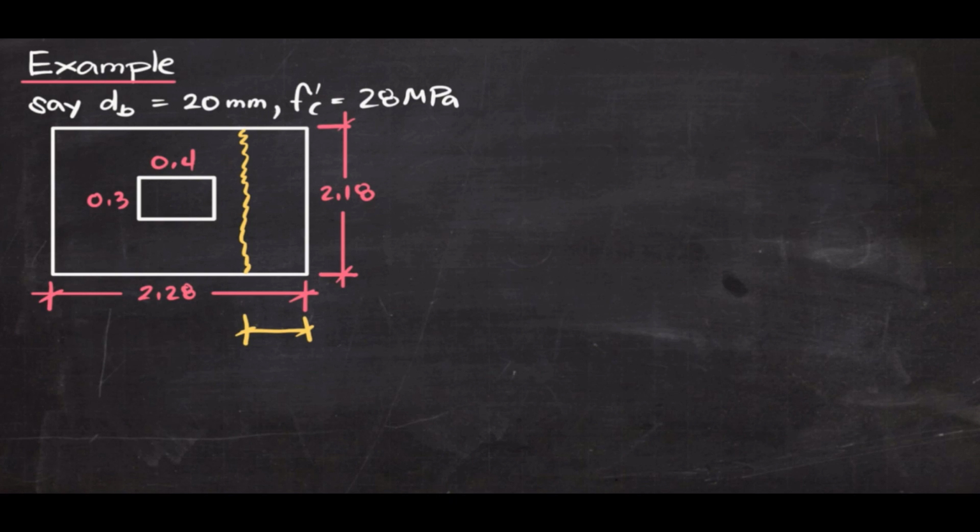Okay, our goal here is to get the thickness. Since the thickness is not given yet, we don't know what would be the effective depth. But if we compute this, what would be the width of this area? This would be 0.94 minus d. Now, from our load combinations, we know that P sub u is 1160, and dividing it by the area of the footing, we get the ultimate concrete stress.